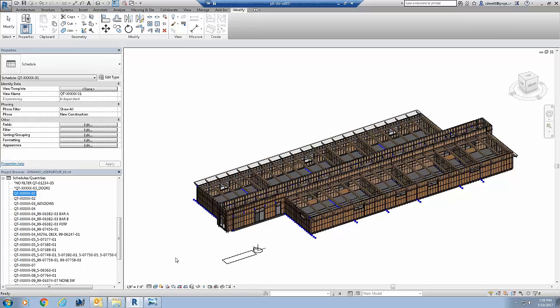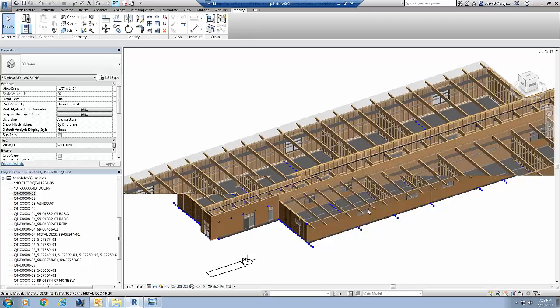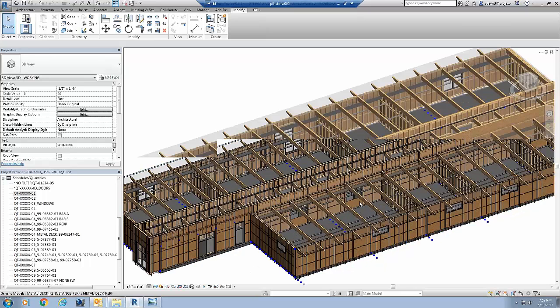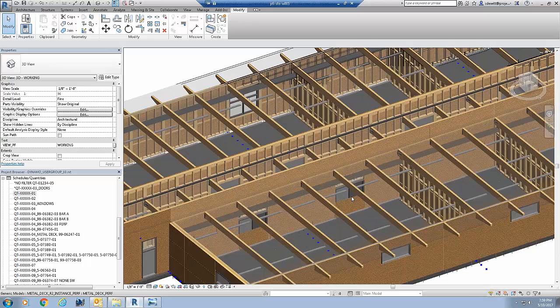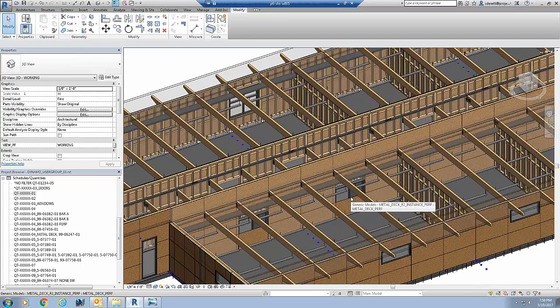I mean, don't get me wrong, it's not perfect. There are certain components that, as an example, we have placeholders. We've allotted window types and door types that we may not have a specific wall panel for yet. What I do is I put a placeholder in, and we call that a .99. Any family in here that has a .99, which looks like this one might be, this is what we classify as a placeholder.